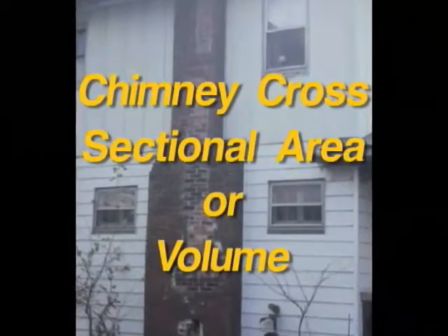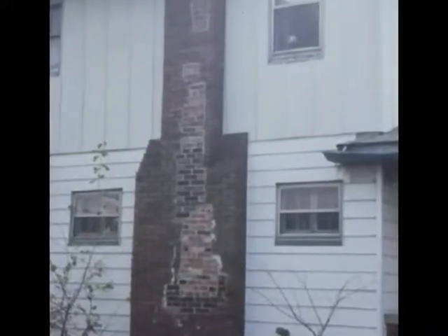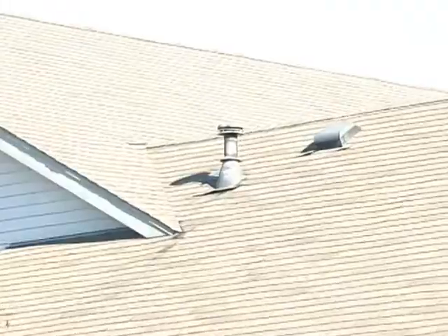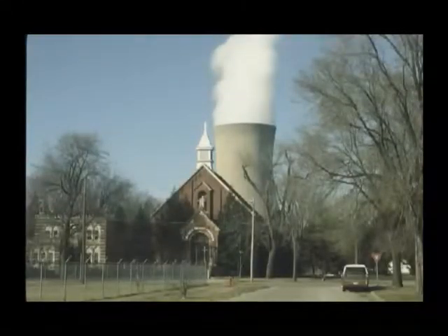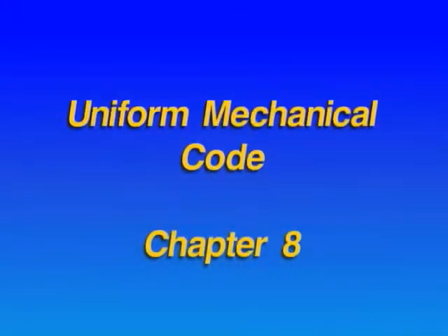Chimney cross-sectional area or volume. A properly sized vent moves all the gases quickly to the outdoors. However, some venting systems are undersized and some are oversized. Both can hinder draft. Always refer to venting tables for proper venting size. Also, see the Uniform Mechanical Code, Chapter 8.